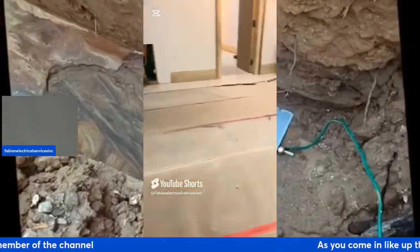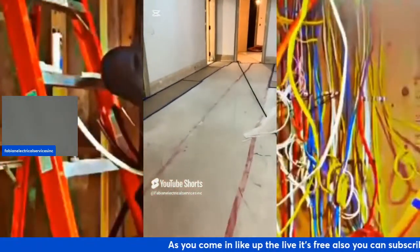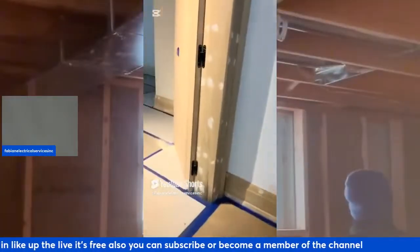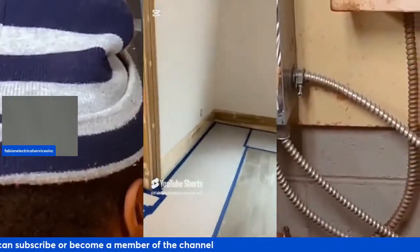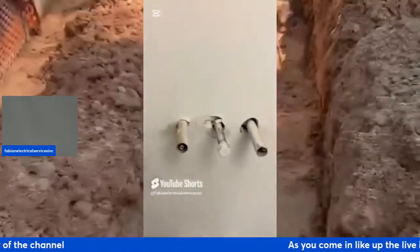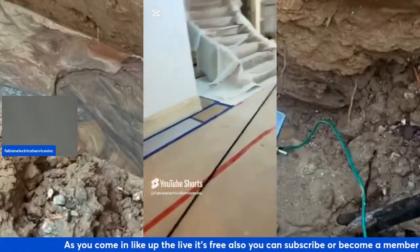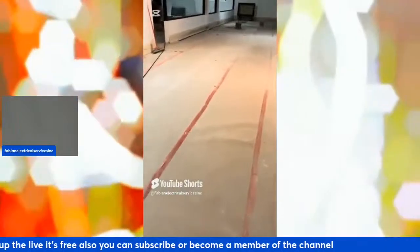You also have anything else that's dealing with normal receptacles in the bedroom, in the garage that's attached to the house, even outdoor, also takes an arc fault receptacle. A lot of times motors don't take one, so you have your pumps. That's a straight up 20 amp or 15 amp, depending on what it's drawing.